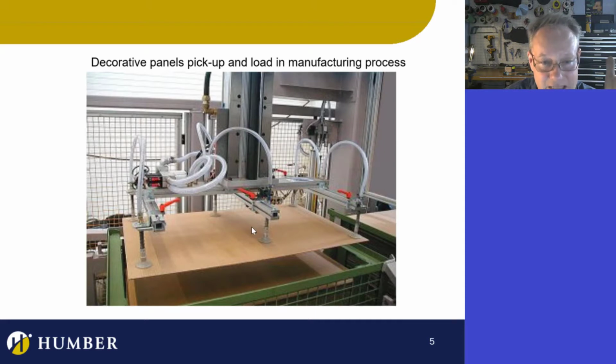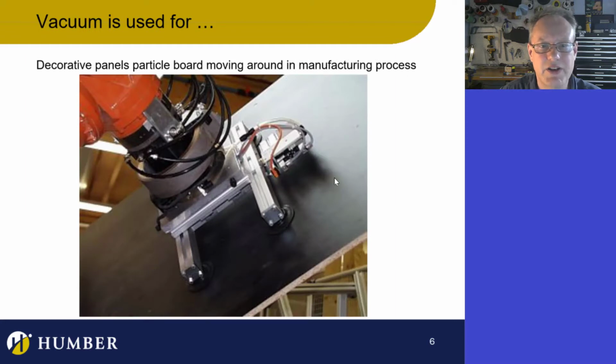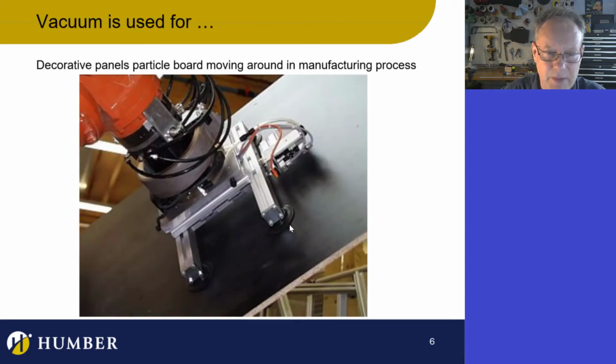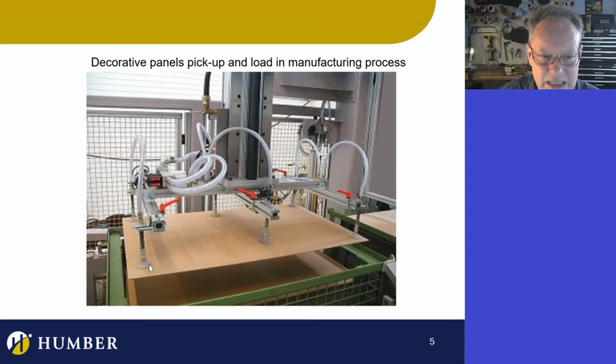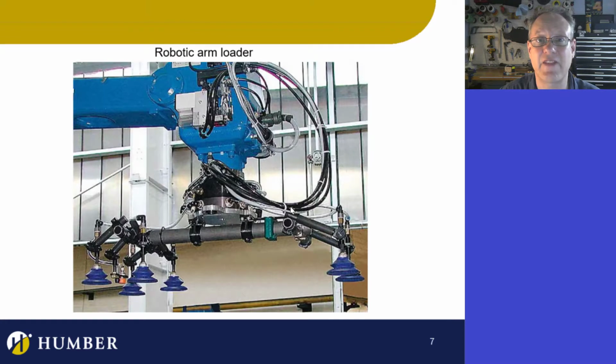And we can see there are 6 of them here to stabilize it, because that's a thin piece of plywood. But it's really large because the vacuum seal isn't going to be very good on just a piece of wood. Okay, so here we go. Here's another piece of wood. Now this is laminated wood. These guys are still pretty big, but this thing's really heavy. These guys have to be the same size as these guys because of the porosity. The vacuum seal really sucks on a piece of plywood, but on laminated wood it is a really good seal because it's such a flat surface.